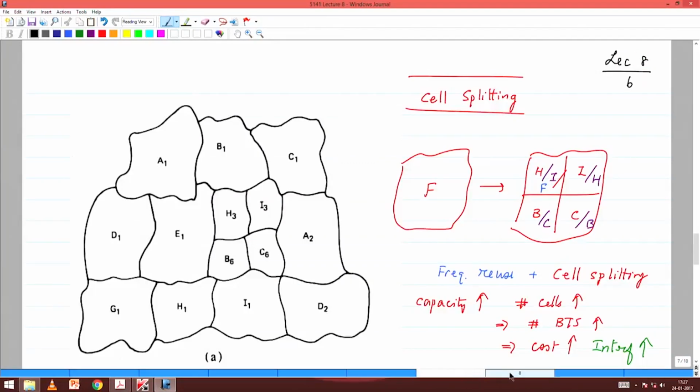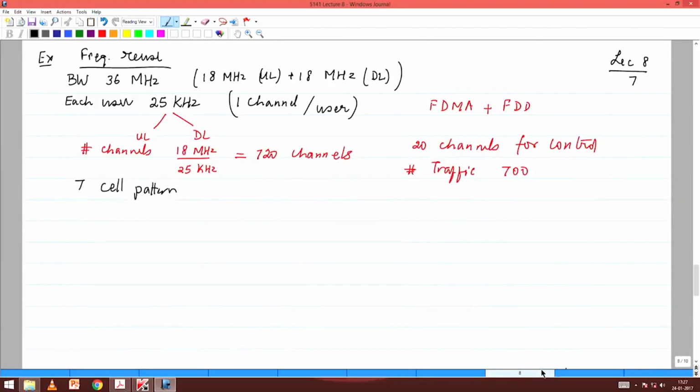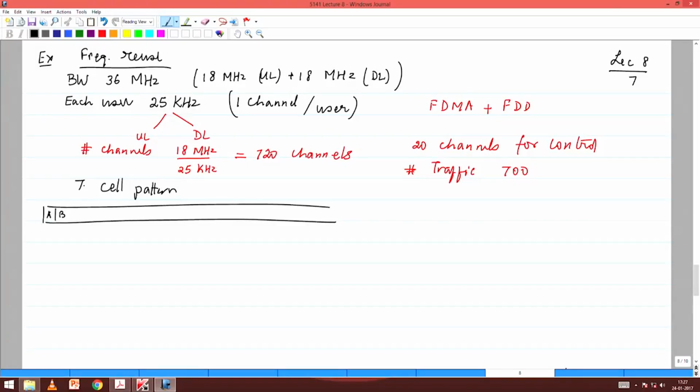And so going back to the example that we are working with, I would have to do my frequency planning in the following fashion. I would take the first frequency A, assign it to cell A, then B, C, D, E, F, G. Why am I not giving A? Because that means I will get adjacent channel interference. I don't want that. So A, B, C. So the next frequency that is used in cell A comes here. So this is also going to A, then this B. You can see how the pattern will repeat.